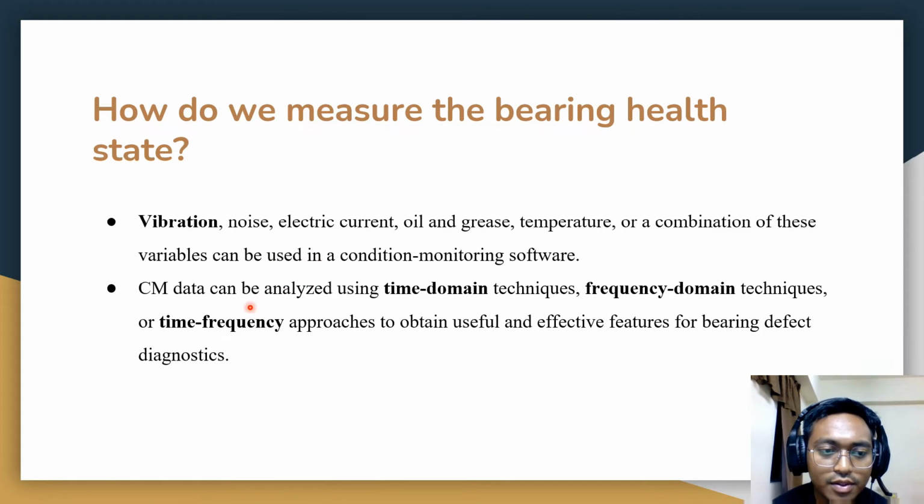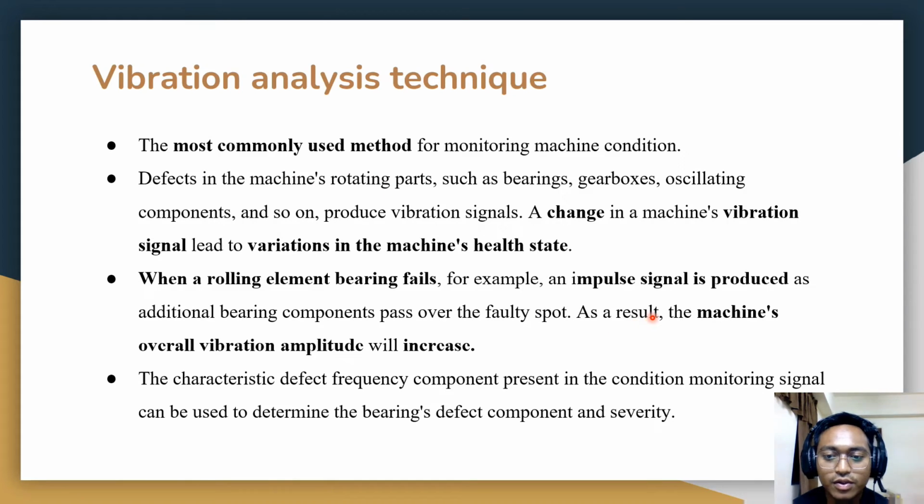Condition monitoring data can be analyzed using the time domain technique, frequency domain technique, or time-frequency approach, which provide useful data for bearing defect diagnostics. The method that we choose to explain about bearing condition monitoring is the vibration analysis technique. This is because it is widely used for monitoring machine condition.